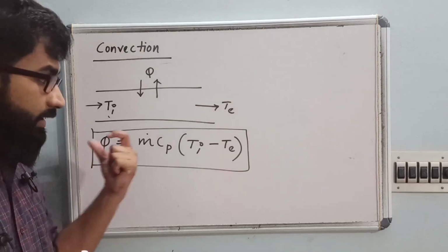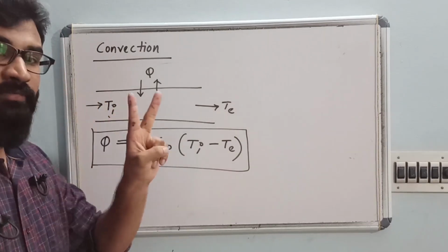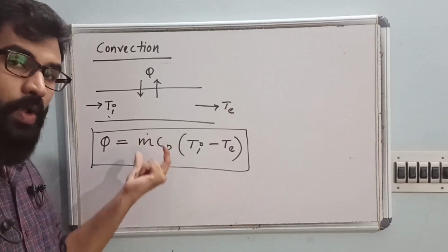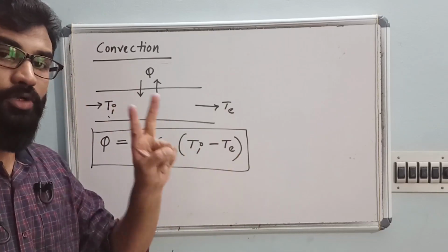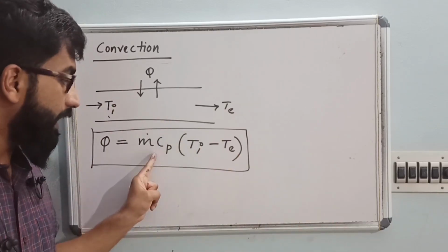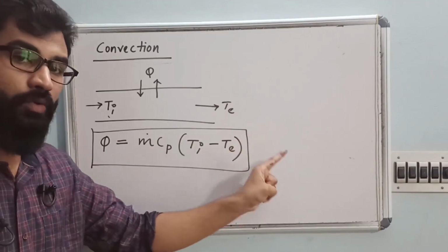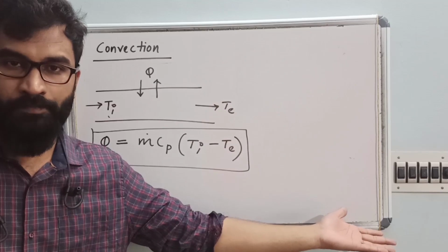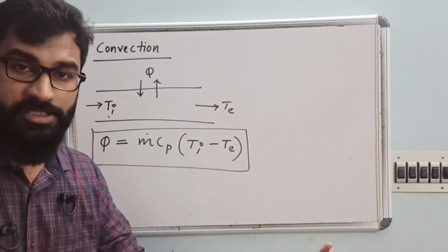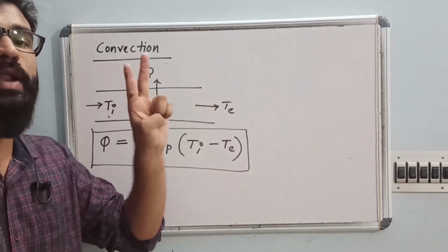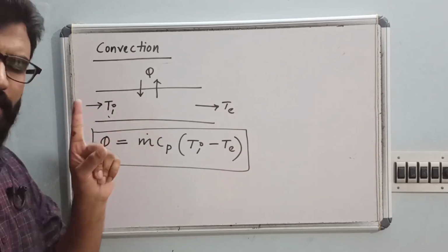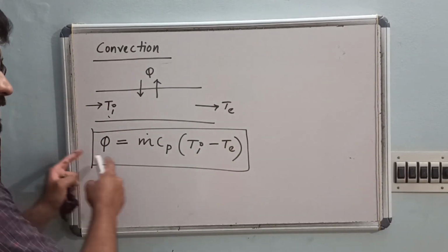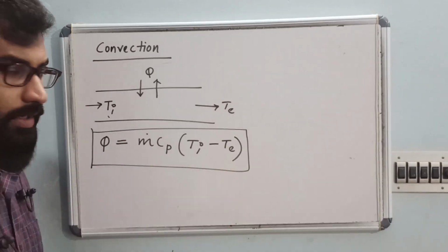If you remember, in a heat exchanger you will have two fluids, that is hot fluid and cold fluid. So accordingly you may have two energy balance equations: m dot c Cpc delta T equal to m dot h Cph delta T. I hope you remember. Right, you have two energy balance equations. Why? Because in a heat exchanger you are having two fluids. In convection we are considering only one fluid. Clear? Now, this equation is always there. You can calculate, no problem.